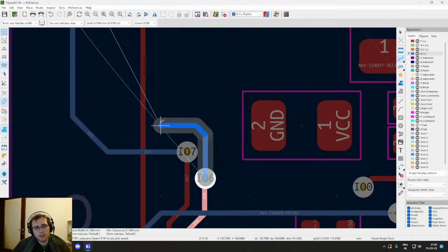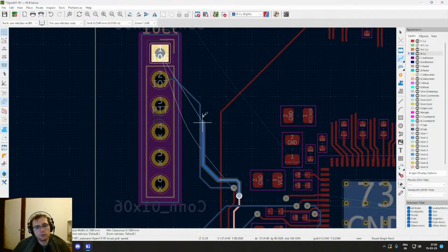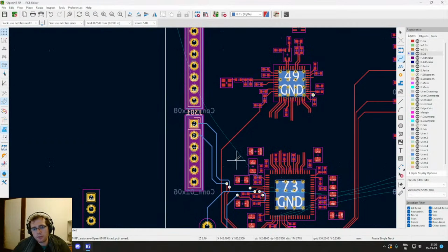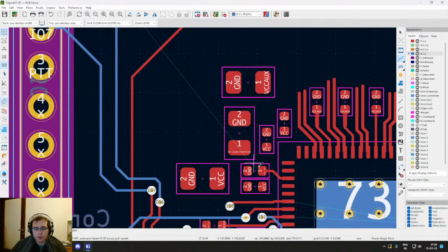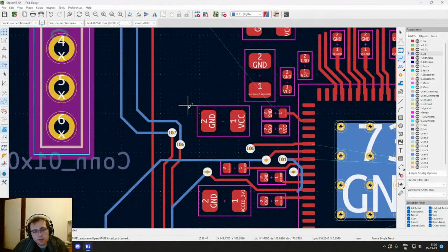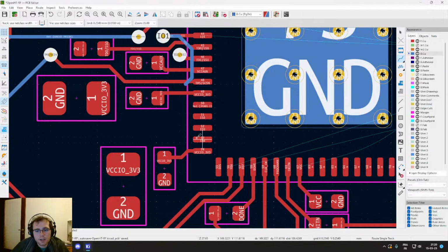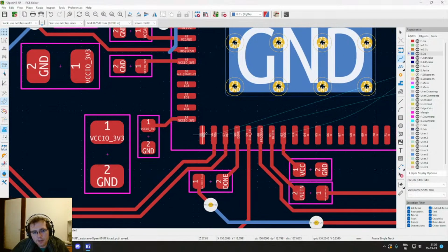So the I/O lines, those are the GPIOs that were deemed unused on the FPGA that we decided to route to the MCU in case we need them for some reasons later on. So we will, for example, need one line for an IRQ mechanism so that the MCU and the FPGA can exchange data via the SPI bus at a suitable speed.